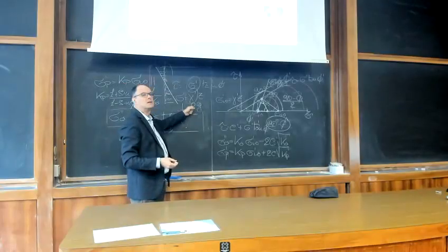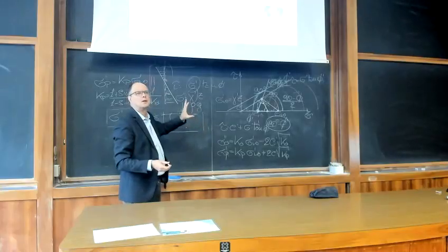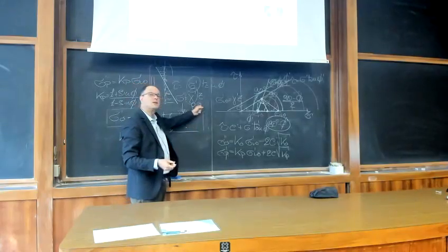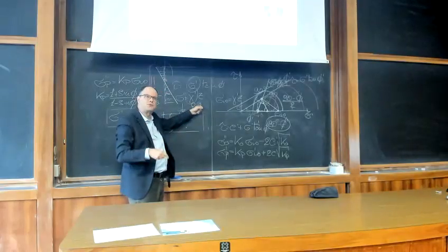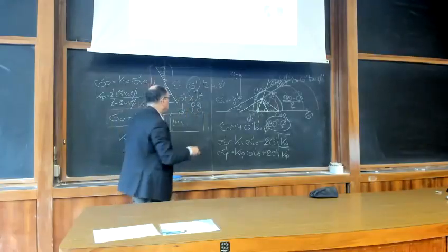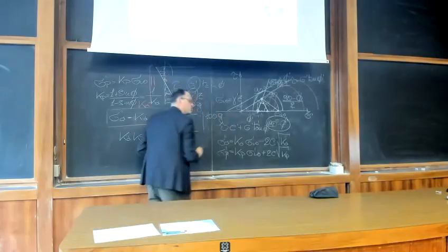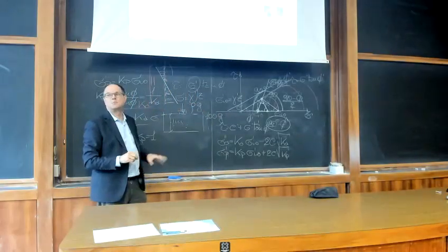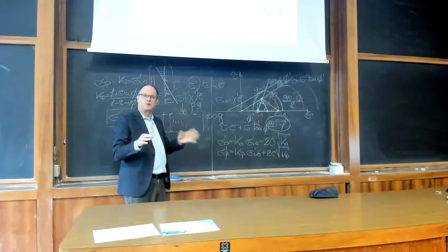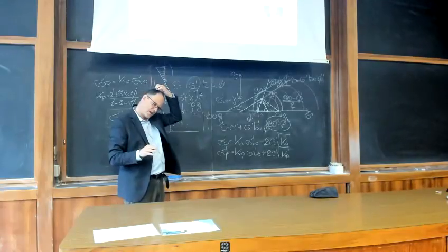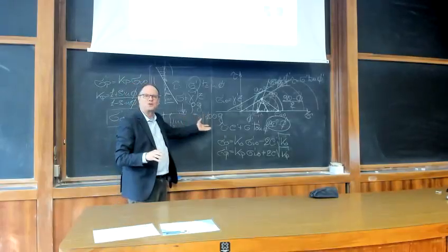So the density is typically the same. You have to reproduce the same density that you have in the field, but you can increase g. So by spinning and generating this centrifugal force, you can reach g levels sometimes greater than 100 times g. This means that if you are there, you are under 100 times your weight, which is not nice and certainly not bearable for a human being, but for the soil, yes.